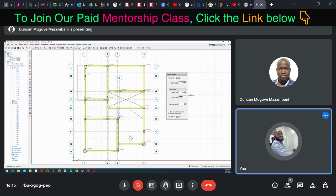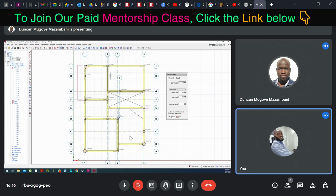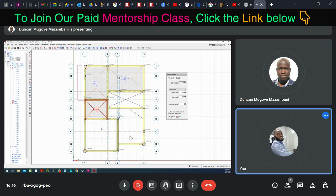Then click on the panels and the slab will insert automatically. Just click on the center of the panels. But where you have staircase, don't put slab there. That place should be void. And here, this one is a void.